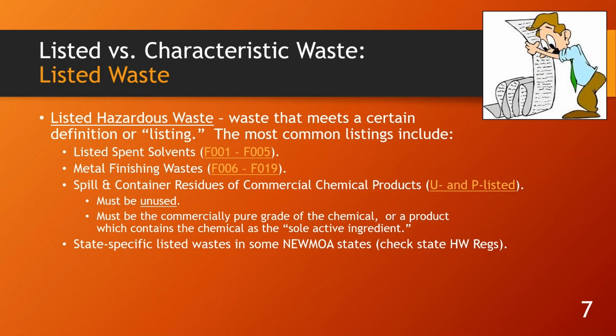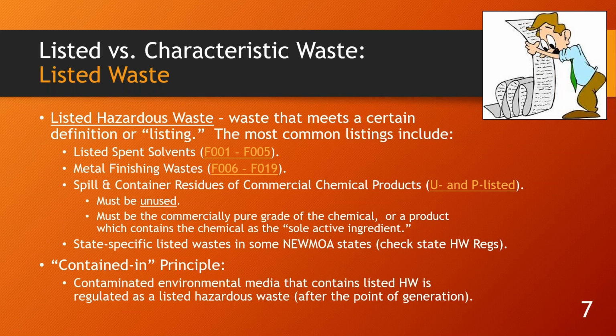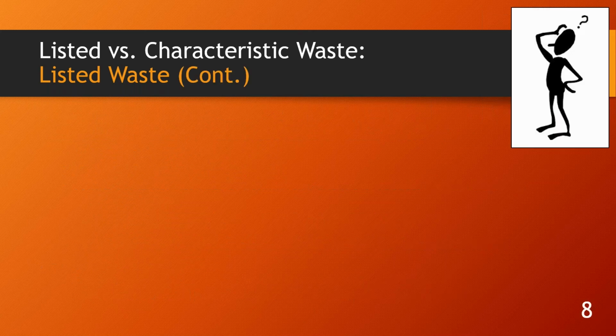So if a small amount were to spill from a TCE drum, any TCE in whatever it spills into, that is all hazardous waste, in theory, regardless of what the concentration is. However, we do get into the contained in principles. So contaminated environmental media that contains a listed hazardous waste is regulated as listed waste, as I just mentioned.